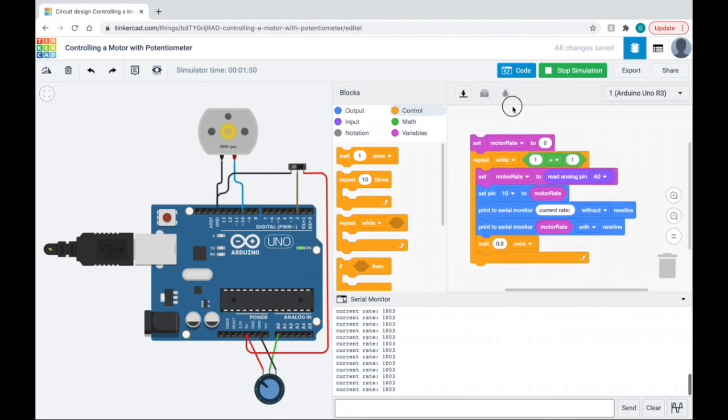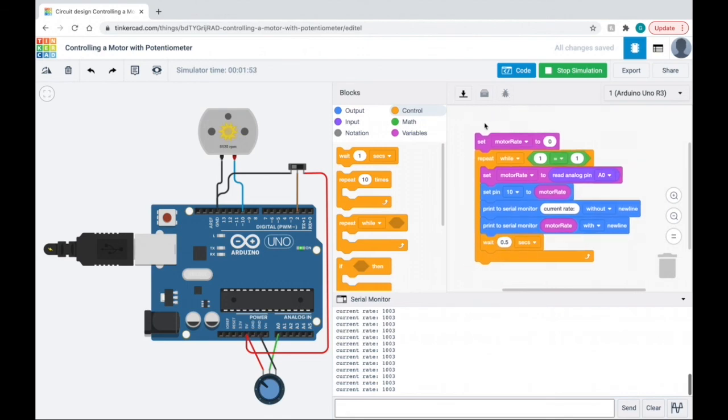This way you can implement any function that you want with the coding blocks. You can create additional conditions to take care of additional inputs and outputs, and do the functions you desire. I didn't implement the switch here, but that is basically a two-state button that is either off or on. Off is 0 volts and on is 5 volts. So you need to add this function into our algorithm here to implement the second task of our lab.